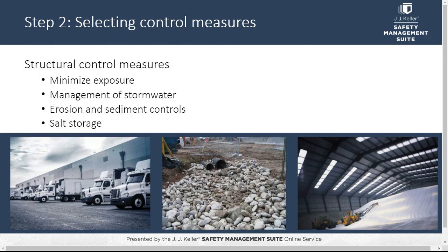And similar to the management of stormwater are erosion and sediment controls. In general, erosion control measures focus on preventing soil or sediment from becoming mobilized. These are the most common control measures in construction site SWPPPs, but they can also apply to multi-sector sources too. Erosion control measures that can prevent the movement of soil should be considered first. This includes grading, seeding, mulching, and sodding.